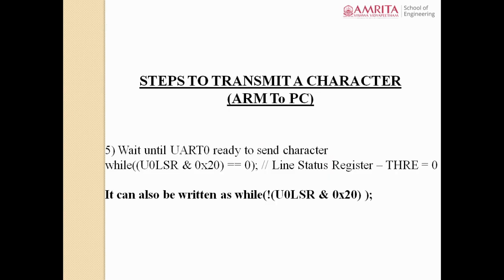How will you do that? That is done in the previous step, the fifth step. You are checking whether UART0 is ready to send a character. That means you are checking whether UART is ready to receive my next character or not. How will I check whether it is ready or not? By checking whether the transmit shift register is empty. If the transmitter shift register is empty, that means whatever data you have previously given to that register has already shifted out, so I can give the new data. So you are checking whether the transmit shift register is empty in order to identify whether it is ready.